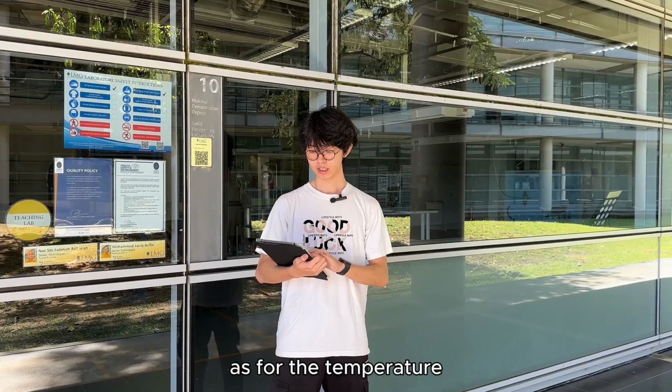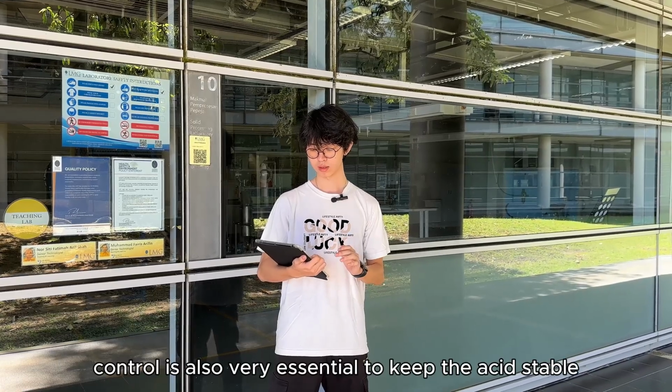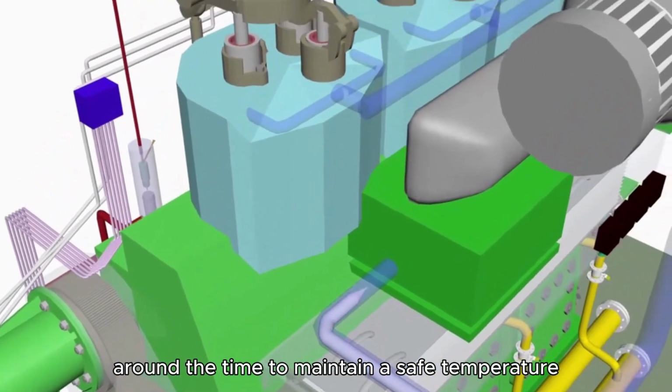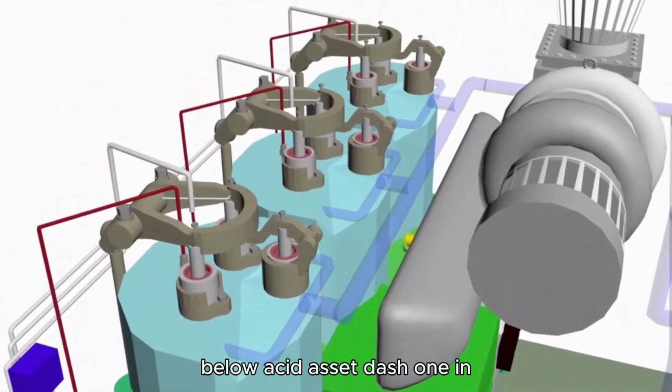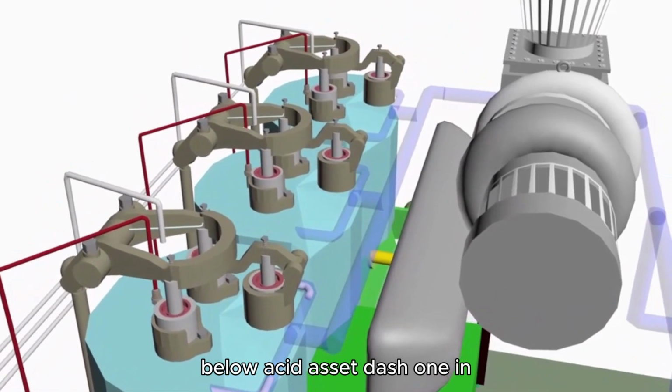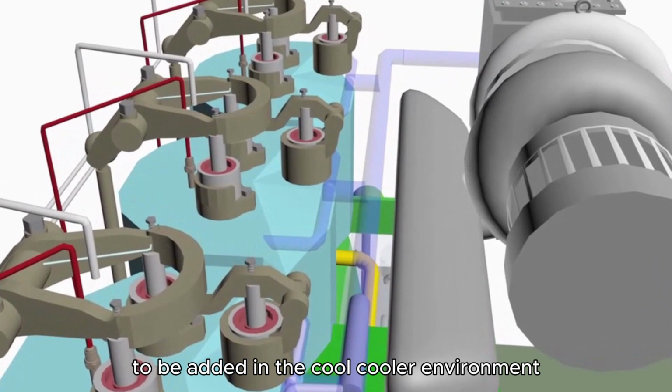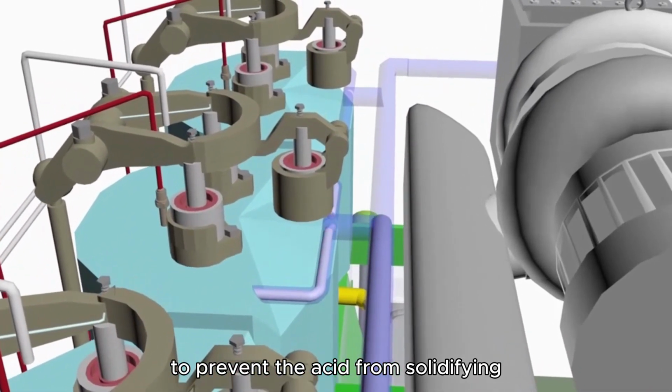The size allows us to store enough acetic acid for the plant's needs and makes maintenance easier. As for the temperature control, it is also very essential to keep the acid stable. So we use a water jet cooling system around the tank to maintain a safe temperature below the acetic acid flash point, as well as insulation liners to keep the temperature steady, and also heating pads to be added in the cooler environment to prevent the acid from solidifying.